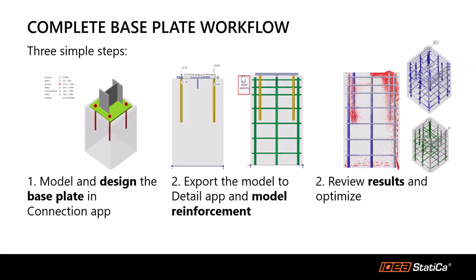To simplify this presentation, I summarized the process in 3 simple steps, all right? So from the connection application, we'll start modeling and design the base plate, including anchor checks using ACI code formulas. If your anchors are failing for concrete breakout, either tension or shear, ACI gives the option to utilize anchor reinforcement. And that is when you will need to design anchor reinforcement, and this is a time where our new integration with IDEA StatiCa Concrete solution comes into play.